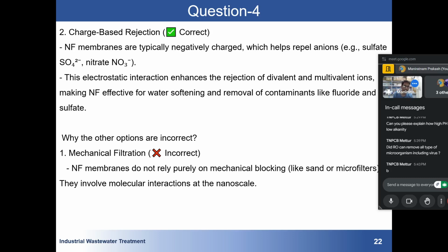So it is said that for fluoride removal, nanofiltration works very well. But the problem is that it is very costly. Use of nanofiltration to treat fluoride is very costly, so that's why it is not used. You might not have heard that in any normal village or at any other location people are using nanofiltration to treat water. The only reason is there is no money.